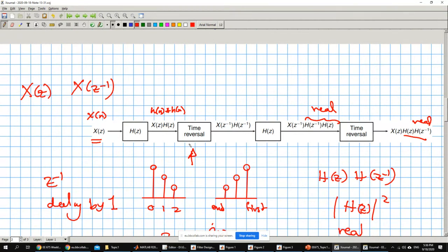This means you have to have your whole signal in order to filter any part of it. Imagine you have an application in ECG, where you want to design a digital filter that would work online in real time. As the ECG signal is coming, you're filtering the signal and producing real-time output. Okay? Can you do that with zero phase filters?